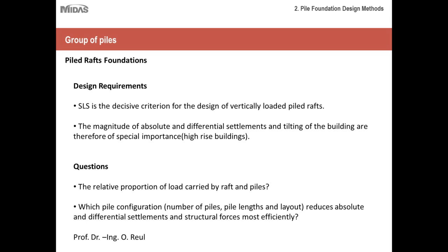Then let's move on to the design requirements for the pile raft foundation. As I mentioned earlier, SLS or serviceability limit state is the decisive criterion for the design of vertically loaded pile rafts. The magnitude of absolute and differential settlement and the tilting of the building are therefore of special importance, especially when you're dealing with a high-rise building where you don't want relative settlement to occur between the towers or the buildings to sway and hit each other.